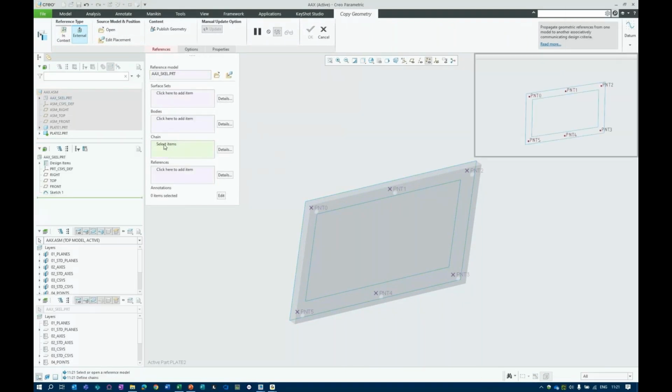Chain, which is easy to see as well. Why are we using this window here? Why, if you go into external, does it automatically open this window? Because I have those lines here in my main window 2 times. I have it for my skeleton, and I have a copy in my plate 1. And therefore, it's easier to go into that window. So I see only what I can select in there, and only directly linked to my skeleton. Otherwise, there's a possibility that we again start making references to other parts, which is of course unwanted.